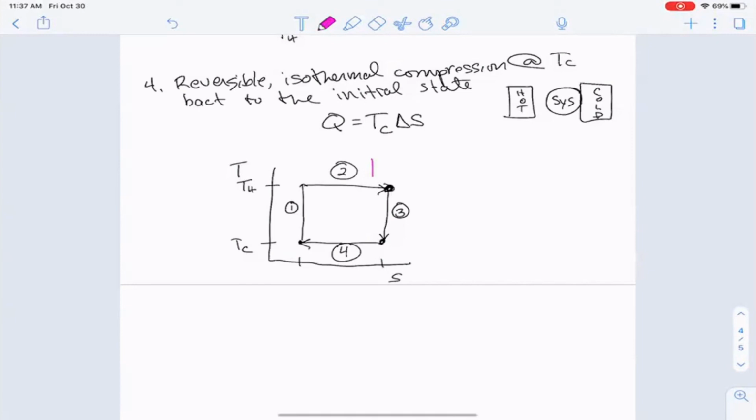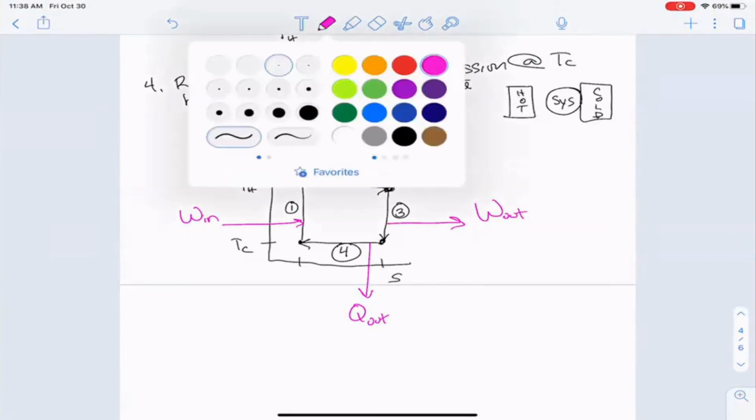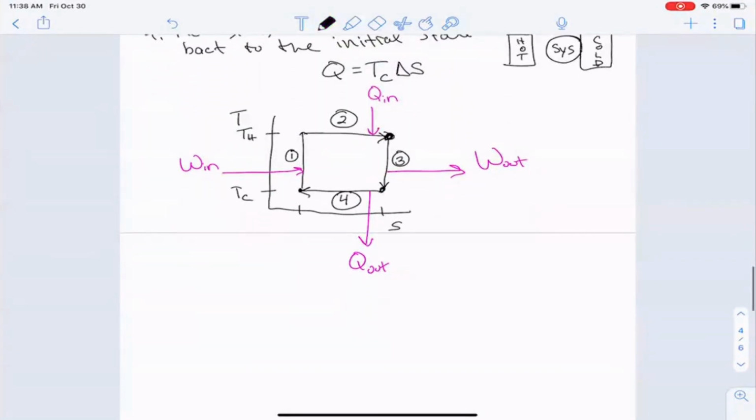We're going to use that to our advantage, because here we would think this is where we put heat into the system. This is where we removed heat from the system, essentially by putting it in contact with the cold reservoir. Step one is when you do a compression. So we might think of this as work that we had to do. And this is the work in step three that we want done by the cycle. And if we wanted to think about this, really where we add energy to the process is only here. In a real cycle, W in is not real, because the piston cylinder is already going to be moving. So in essence, whatever we put in, we just simply can't get out.